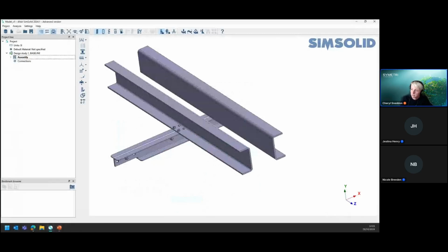So we jump back into SimSolid and we go back and click on the project tree here. It will give us access to the different types of connections. Now, we're going to be working with automatic connections, but we do have the option for manual connections. We also have the option for things like welds, where we've got spot and laser welds and seam welds. We do have the option for adhesives, and we also have virtual connectors, where we've got pins, bushings, rivets, joints.